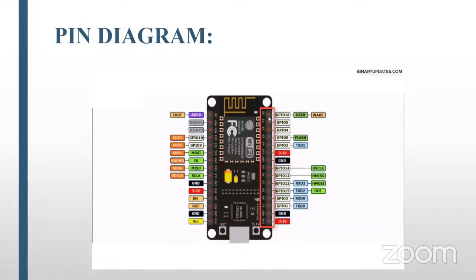If you interface two or more sensors with the ESP8266, we definitely need the MCP3008 external ADC IC. That ADC IC is also a 10-bit ADC, and its value is also from 0 to 1023.